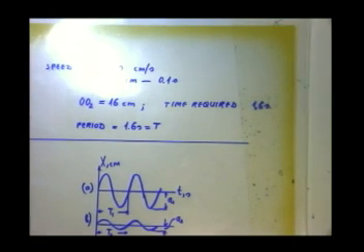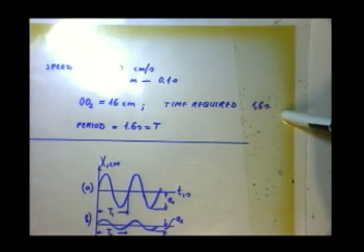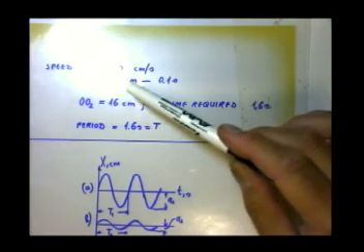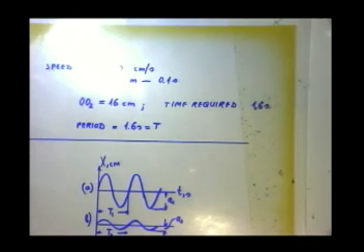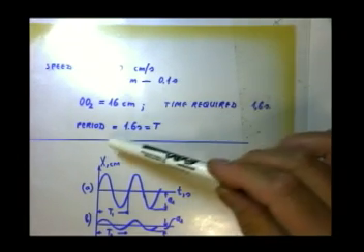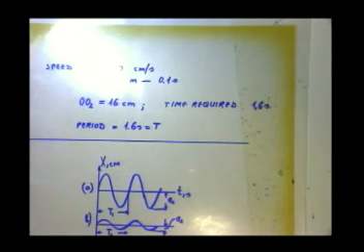So that means that in order to get from O to O2, I need 1.6 seconds, because it's 16 centimeters, and 1 centimeter is 0.1 seconds. So period equals 1.6 seconds. That is how I found the period. I found that in this system, the vibration was 1.6 seconds. In 1.6 seconds, the system's behavior is repeating itself. That is how we found it.